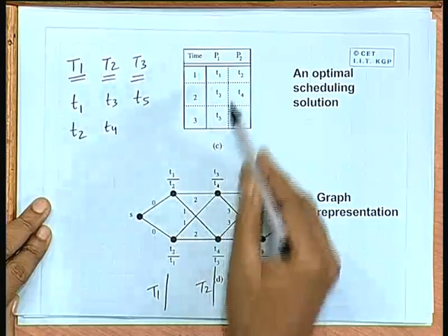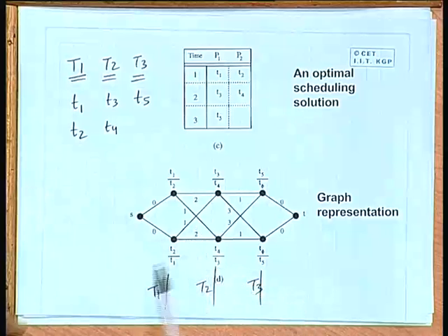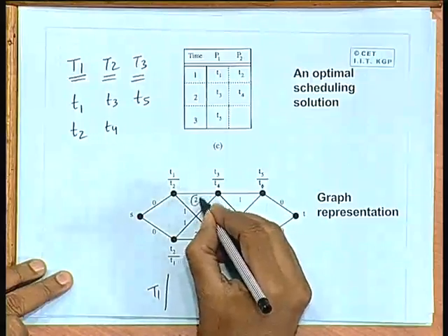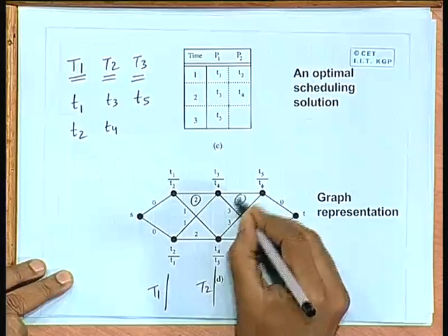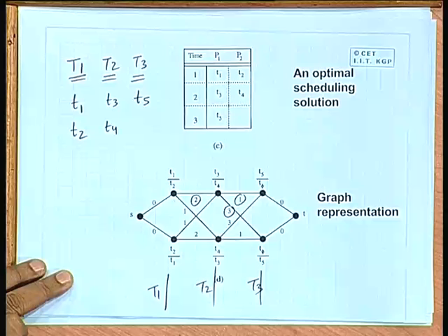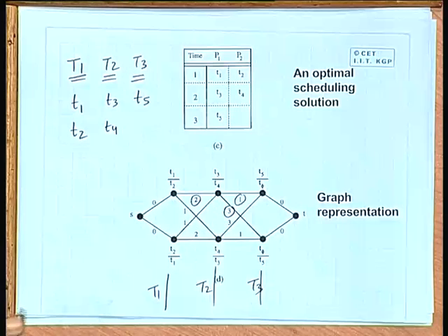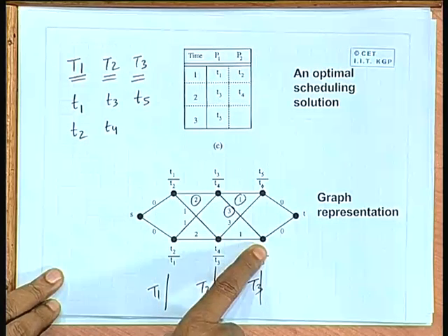Of course, I am not showing you how the weights are coming, but the weights indicate how many vias you require between the adjacent layers if we do the assignment like this. Say some of the edges are labeled as 2, some as 1, some as 3. 3 means you require 3 via connections if you follow this followed by this.